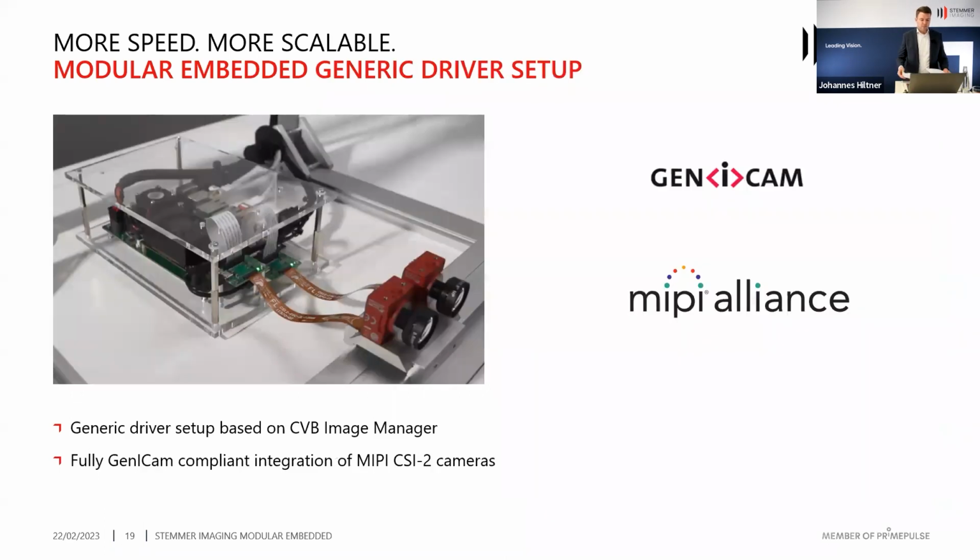The next quite interesting USP is that we are able to acquire images from MIPI cameras using a GenICam compliant driver setup. This is also a development by Allied Vision. They basically provide a GenICam compliant transport layer with their MIPI cameras, and this allows for seamless integration of MIPI cameras into our generic image acquisition engine.